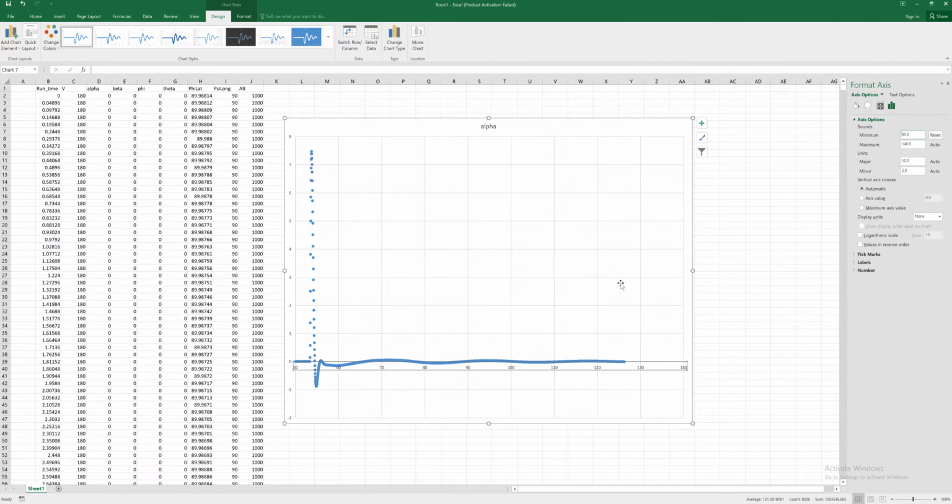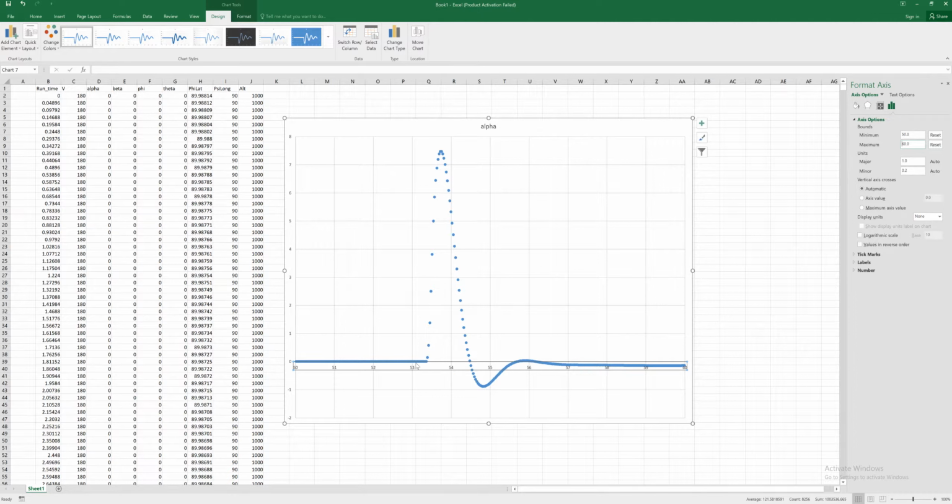Okay, so this rapid change in angle of attack, remember I put in a near step change in elevator. It took less than a second, really less than a fraction of a second, for me to whack that elevator and have it return back to zero. And so we're really getting some step change right in here, but it excites this response in pitch, or in angle of attack. And this is the short period mode. So you can see it's heavily damped. We're only going to get a couple oscillations here before that's all damped out.